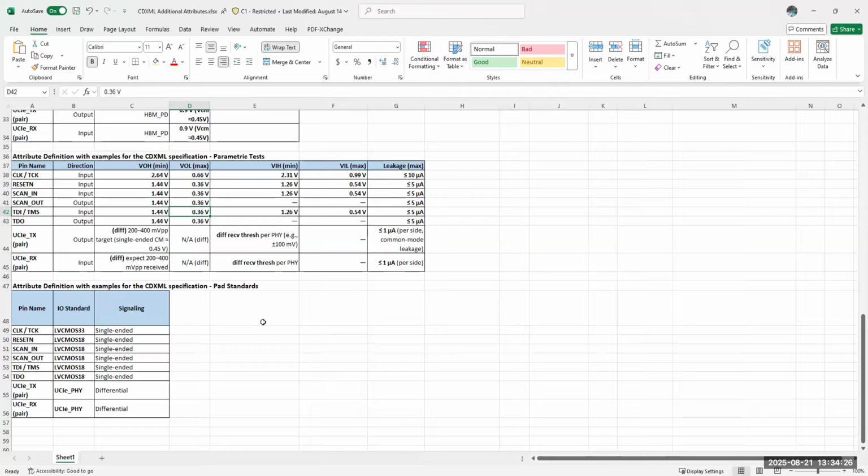Okay. I think the name parametric got me confused because we used to call it boundary scan in Broadcom. So my question is, this table should not be limited to only showing the DFT pads, right? Because parametric test will be for all IOs. Right. It's for all GPIOs and high-speed IOs. Yeah. Okay. And second, the consumer who is going to use this schema will apply it to the entire chip IO. Right.